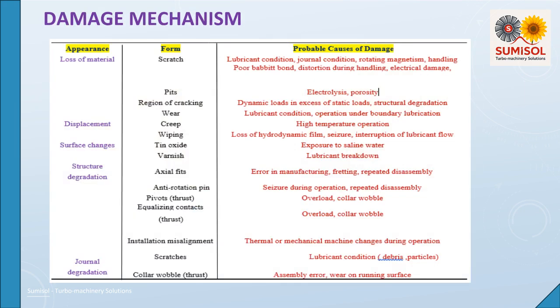Damage to tilting pad thrust bearings is caused by factors like lubrication failure, overloading, contamination, and misalignment. These lead to various damage mechanisms, including abrasion from debris, wiping or scoring from contact, overheating leading to thermal fatigue and coking, electrical discharge pitting, and damage from cavitation or poor assembly.